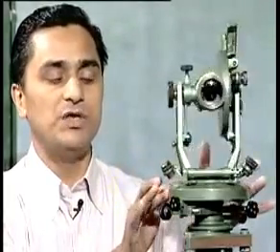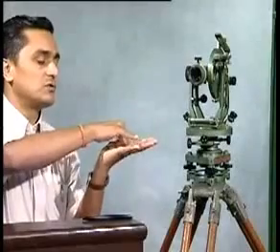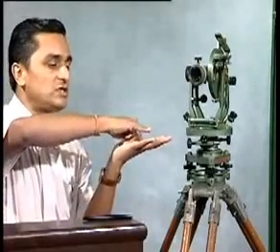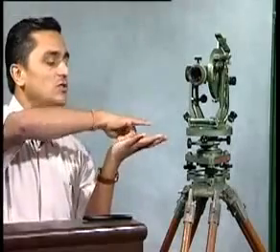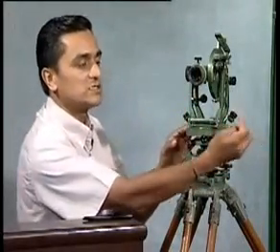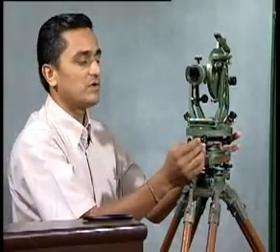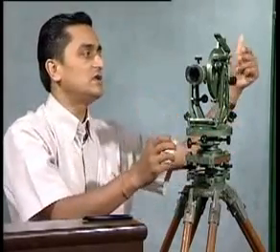Upper clamp is released and I rotate it to B. What is happening now? In this case, if the upper clamp is released, only the vernier will rotate. While I am rotating this telescope, only the vernier will rotate and the angle value will change. So if this angle is theta, it has moved by theta,